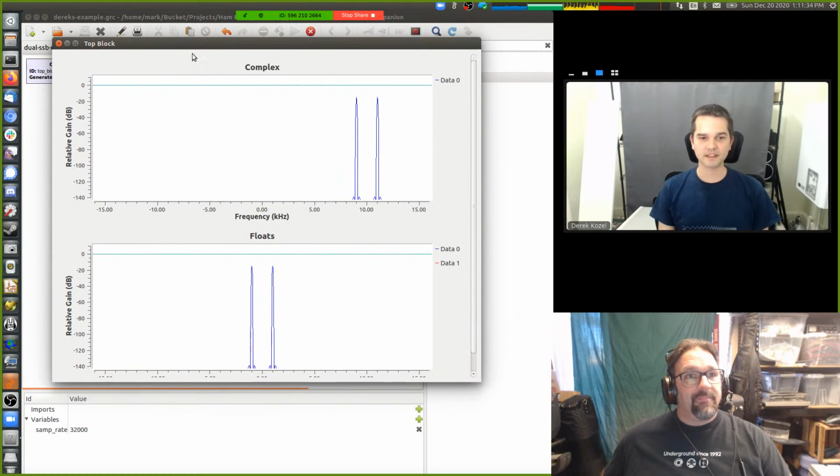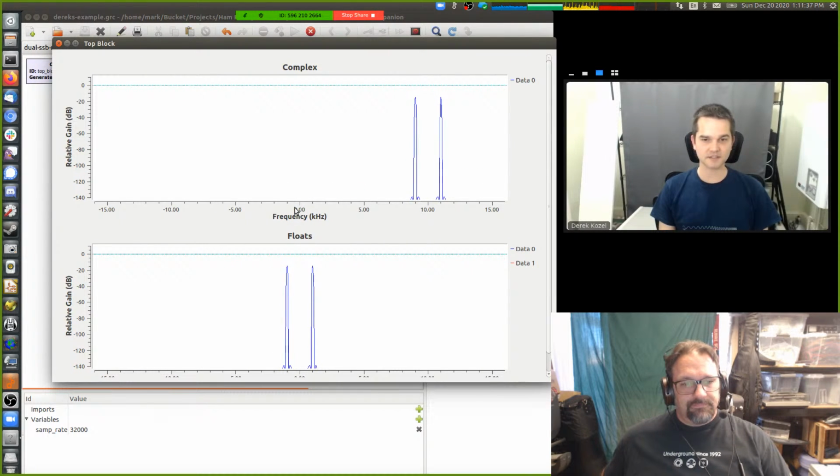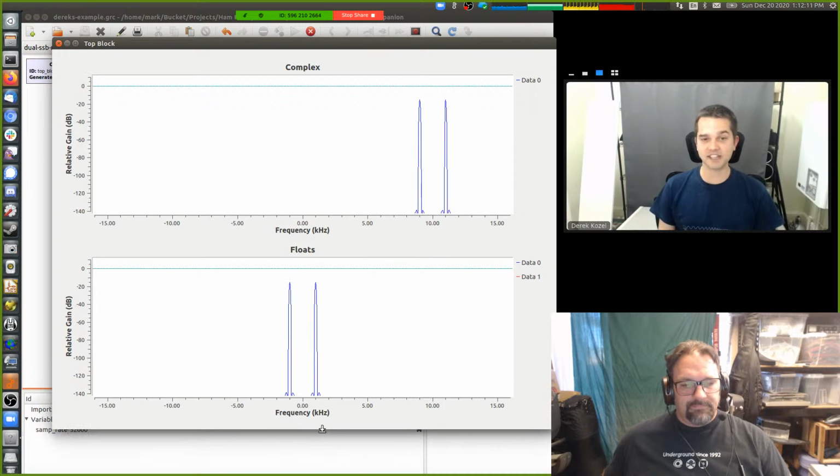Okay. So the fun thing that we have here is, one, your data 0 is just 0. There's no signal there, so there's no frequency content, because it's a constant value, so it's unchanging, it has no frequency, and it has an amplitude of 0, so it's not a DC offset. So there's no energy at 0 hertz. In the other component of our input, we have a real-valued sine wave with a frequency of 1 kilohertz, and so it has a valid negative representation of negative 1000 as well.